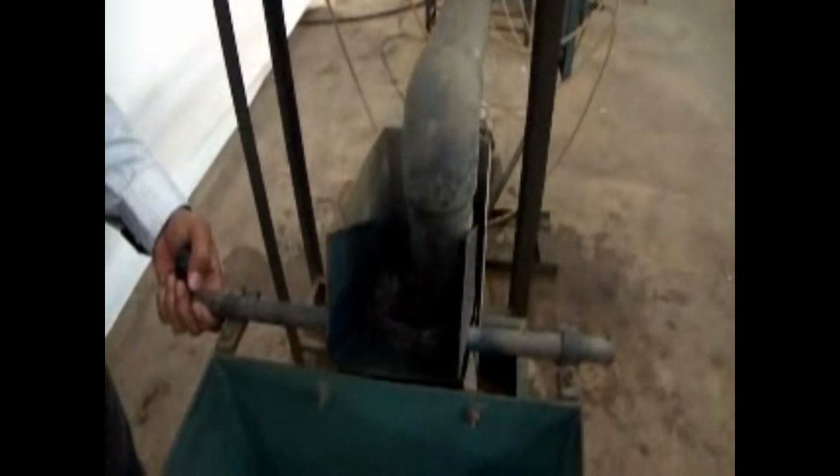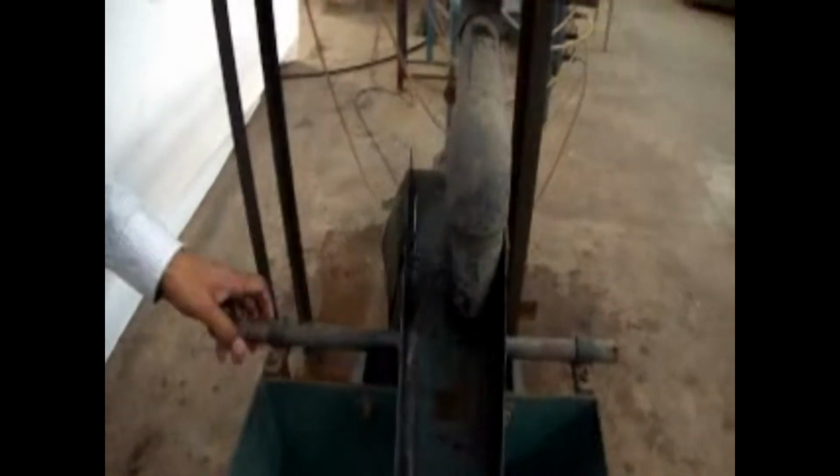And now let us measure what is the discharge per unit time. So volume of water for a certain time, let us measure in the tank. Now let us observe this, what is the discharge per unit time. So we are transferring this flow to this measuring tank, and here we can see the flow. The moment it is coming from 1 to 11, just 10 centimeter rise in head, we will observe. Rise is starting, so let us start.